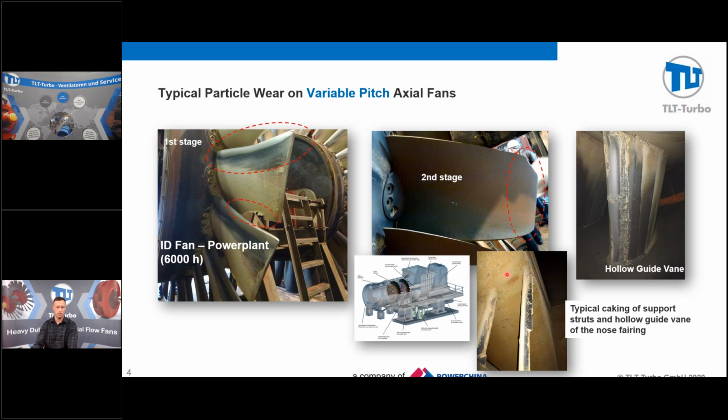So another thing to watch is to look at your buildup as well while you're looking at wear inside of a fan system. Now, some natures that come with this, you're going to see that with this increased wear, you're going to lose fan efficiency. So as you lose blade profile, your pressure is going to decrease, which also is going to decrease your efficiency. Typically, on a normal wear of a fan system that's encountered, as the fan blades wear, you're going to drop your efficiency 3 to 5%. A lot of that's going to be relative to the tip and the blade's tip gap due to the wear, and then losing the performance of the pressure side of the rear fan blade.